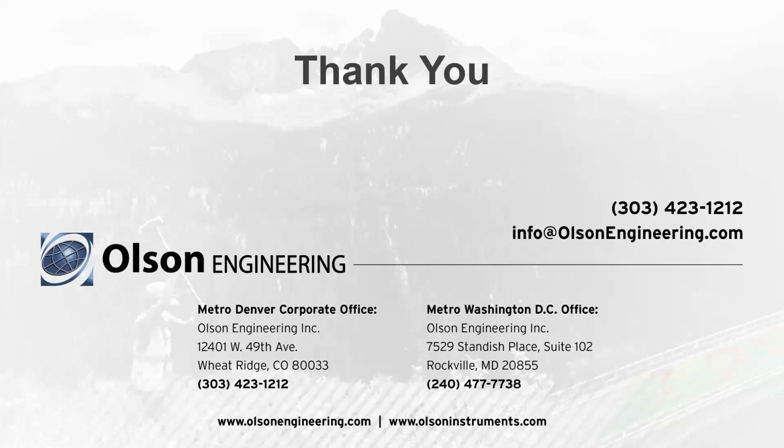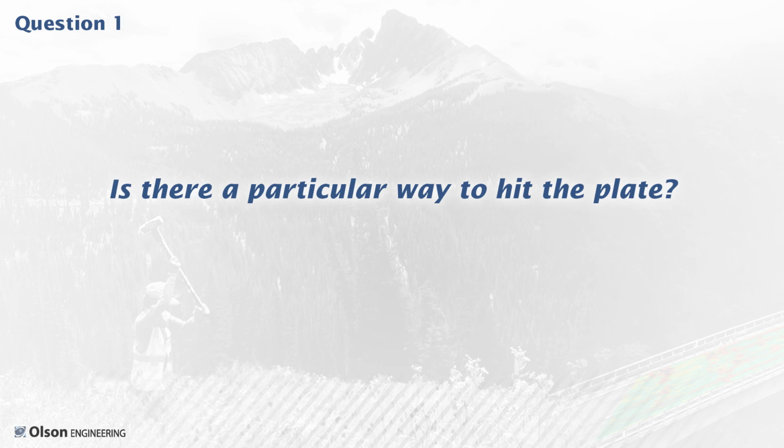Okay, so the first question we have is, is there a particular way to hit the plate? Yeah, so there is a better way. In an ideal world, you'd hit the plate once and hard and you wouldn't have any bounce. That being said, if you bounce the hammer, the waves associated with that second hit are going to be offset in time from your first hit. So if you've got a little bit of bounce, that's fine.